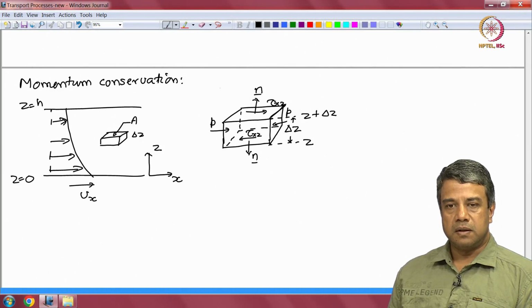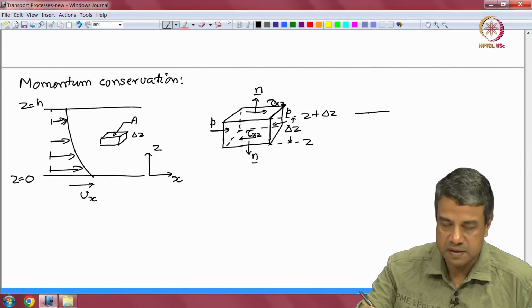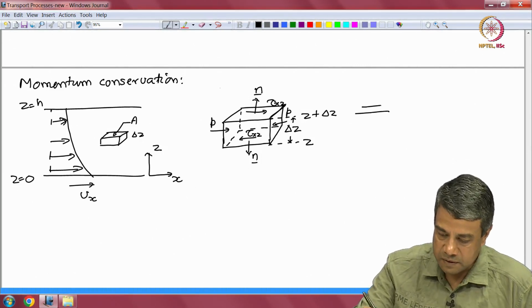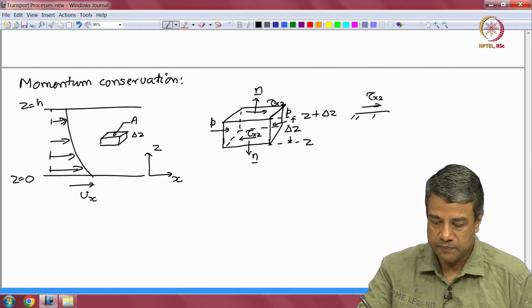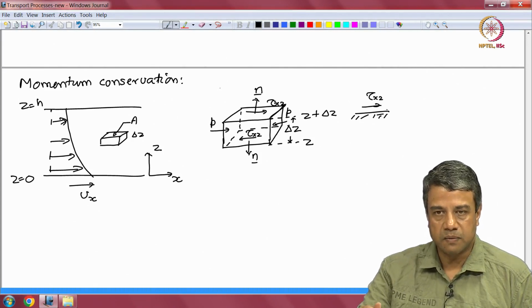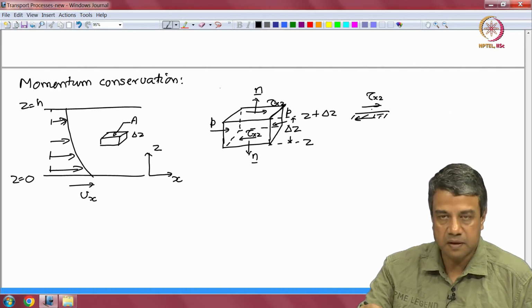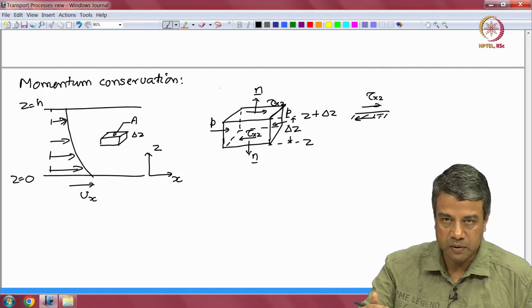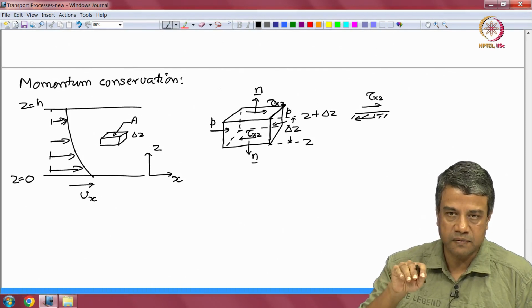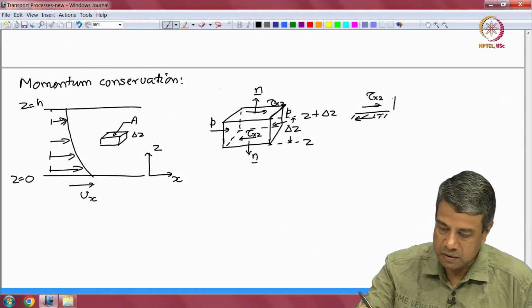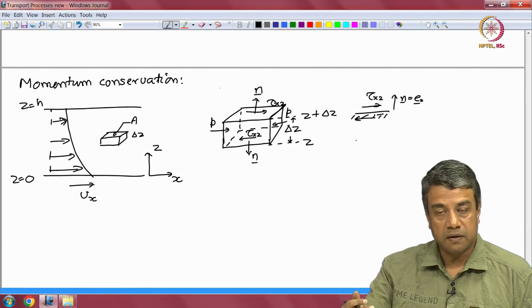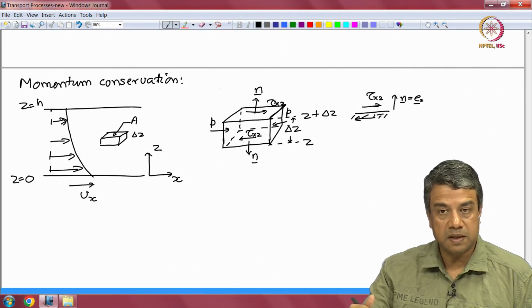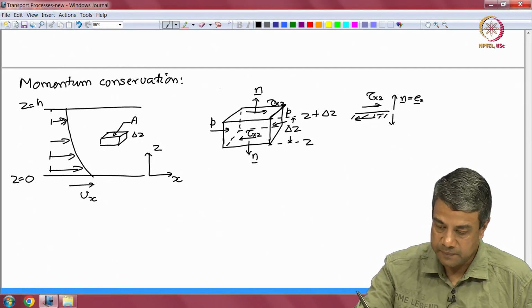Note that if I have the force tau x z exerted on the volume below, then this volume will exert an equivalent opposite force on the volume above from Newton's third law. So, if tau x z is the force exerted on a volume with outward unit normal in the plus z direction, for the volume below the outward unit normal is in the minus z direction.